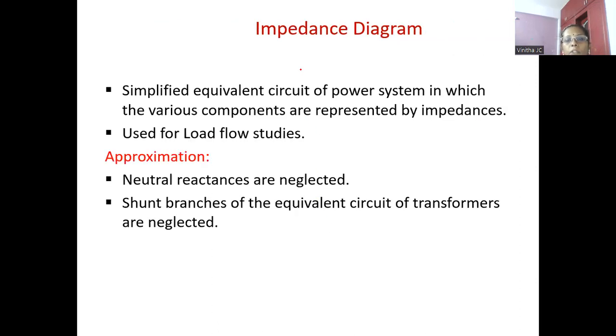Now let us see the procedure to draw the impedance diagram. So why do we need this impedance diagram? Because this impedance diagram is mainly used in load flow analysis. For calculation purposes in load flow analysis, we require this impedance diagram. And to draw the impedance diagram, we require some approximations. So let us see the approximations that are made in this impedance diagram.